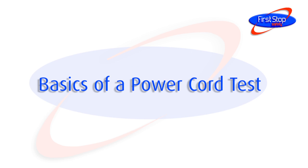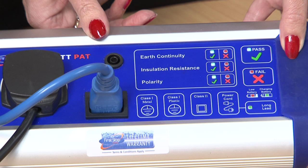Basics of a power cord test. When testing power cords, we carry out the basic Class 1 tests of earth continuity and insulation resistance. In addition, when testing power cords, it is important to ensure that the wiring of the cable is correct. This means checking that the live and neutral wires are wired correctly. This test is usually called the polarity test.